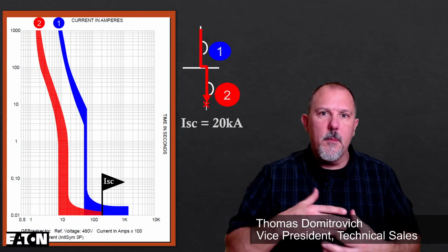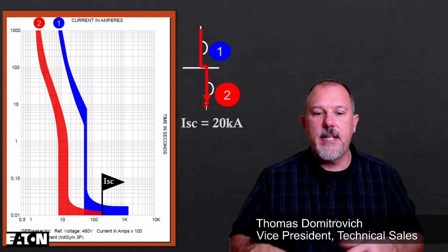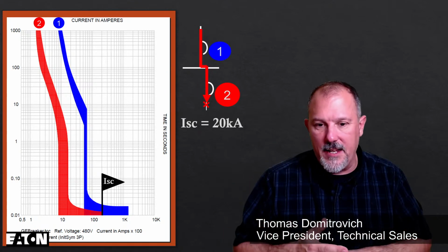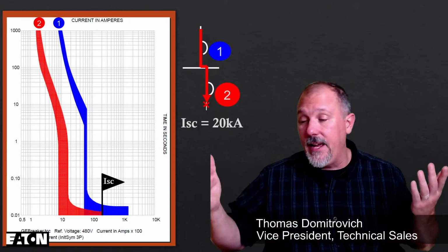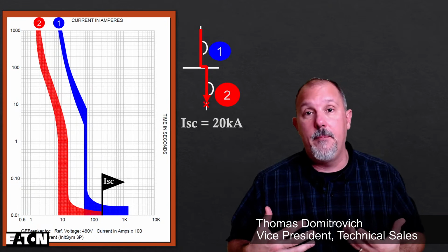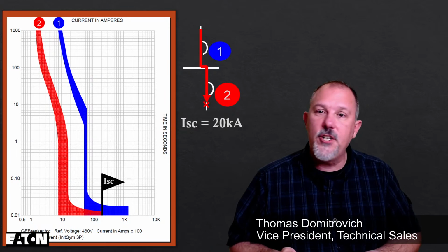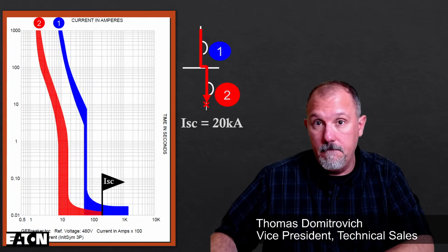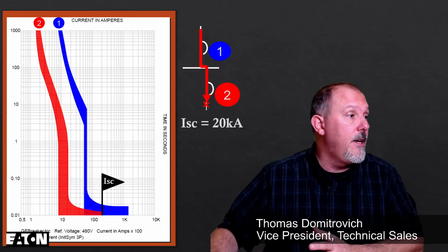But I think the other part of selective coordination is in some cases, you may have someone say, I want to do other options, and I can't because you're mandating selective coordination. But unfortunately, because 517 went to 0.1 seconds, there are a lot of design engineers that are going, hey, I'm going to save some money here. I don't want to lose this order because I'm putting in multiple circuits because I'm worried about reliability. If the code's not worried about reliability, then I'm not going to take that level on my shoulders and burden my quote with the additional cost that the customer's not asking for. Unless the customer is truly asking for the reliability, then I'll start considering those other options.